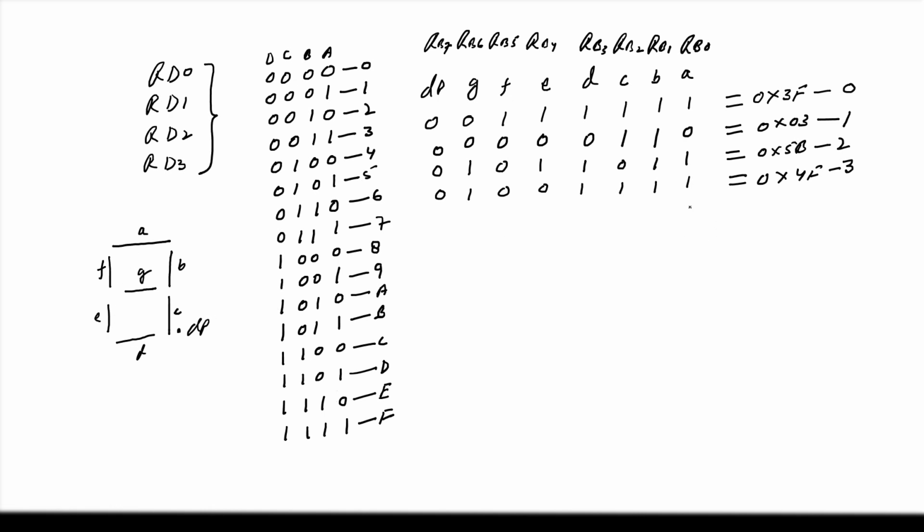So we can write segment A will be off, segment D will be off, segment E will be off and dot point will be off and all other segments, that is B, C, F and G will be on. B, C, F and G, and the equivalent hex number is 66, that is 0x66, and it will display the number 4.